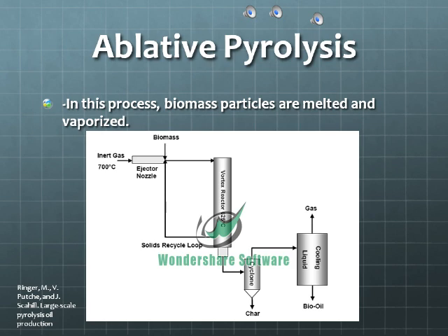The heat within the chamber, as well as the friction from the reactor's walls, is enough to melt and vaporize the biomass. If any biomass solid remains after this, they are filtered out and automatically undergo the process once again. After this filtration has occurred, vapors are then redirected to other sections of the machine where char and other byproducts are filtered out. Finally, remaining vapors will condense into BioOil.